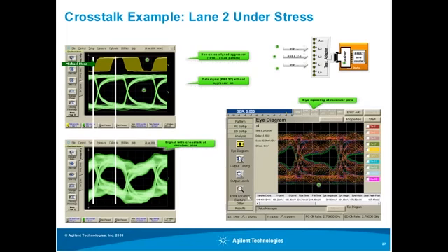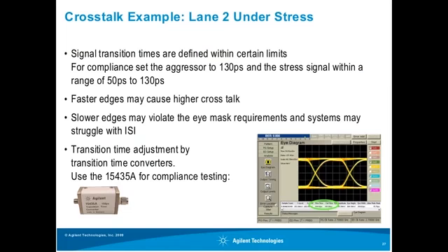So what you measure at the receiver pins on the sink device board is a waveform which looks like this. And you see how the crosstalk adds up on the amplitude, but also causes additional jitter. And on the right, you see the resulting eye opening on the sink device board. So this is really from crosstalk on a real board. So crosstalk has to be added for the compliance test and should also be considered during characterization.